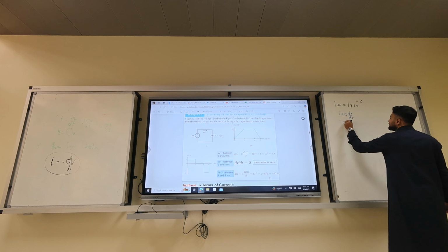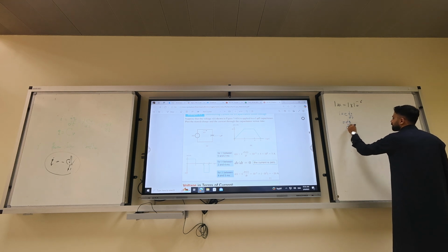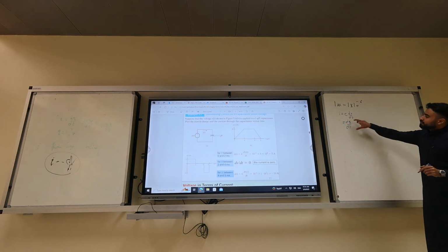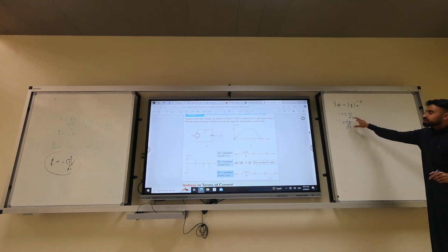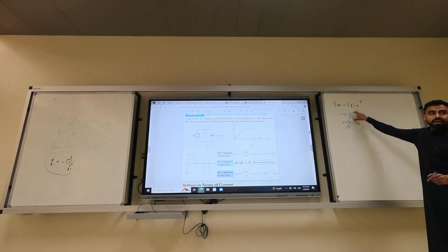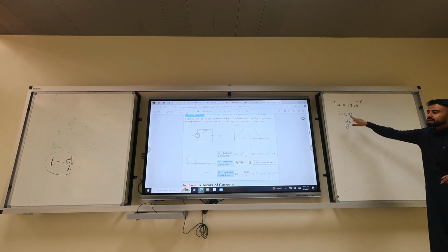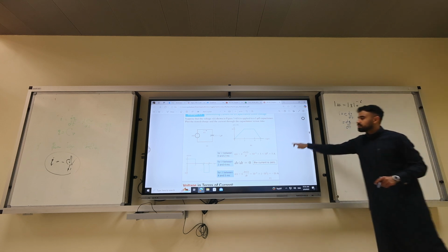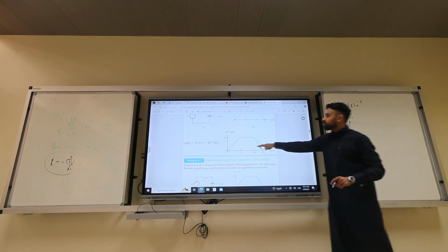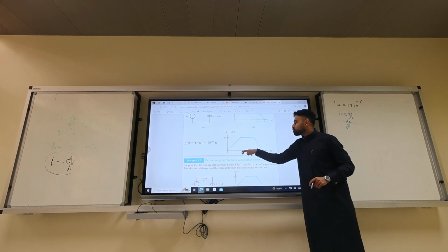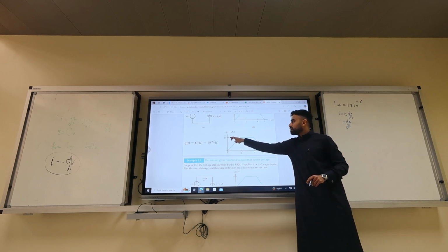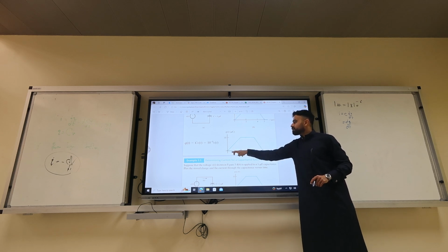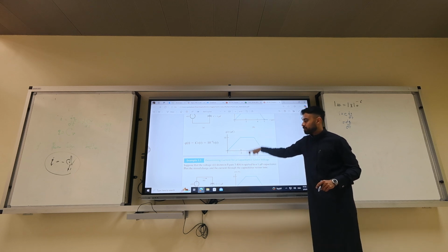Or you can see it's dq with respect to time. So you can either find dq/dt directly, or get the voltage curve, take the derivative of it and multiply it by C. Which one is easier? Well, I think it's easier to get the Q plot. So we want to take the derivative of that plot. From 0 to 2, what's the slope? 10 over 2 is 5 micro.